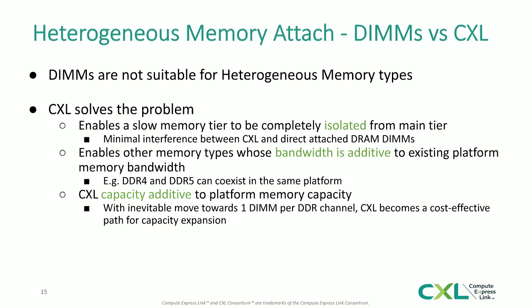So we're not going to be limited by the number of DIMMs per channel or even the number of ranks per channel, because we can scale those independently of the standard DDR channels. Ultimately, we also would expect that this should be a more cost-effective approach to scaling, because we can focus on optimized buffering solutions for CXL that don't have to rely on large parallel high-speed buses.